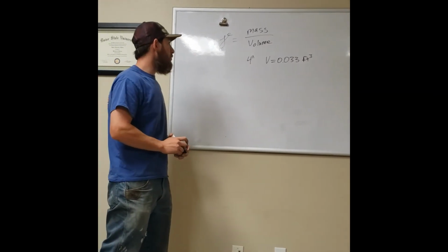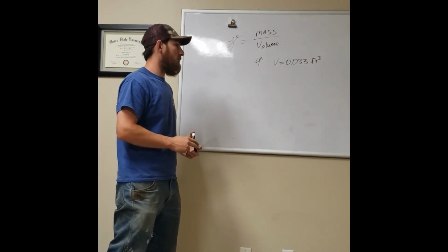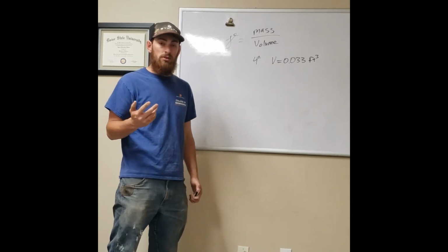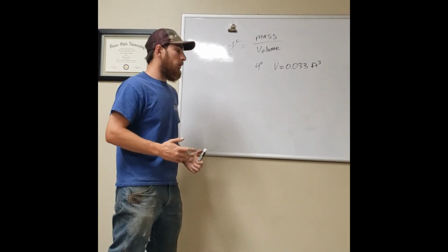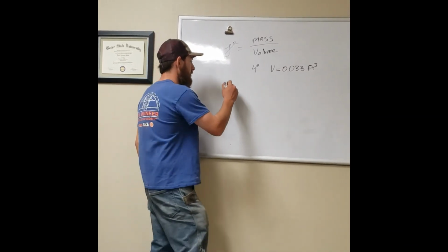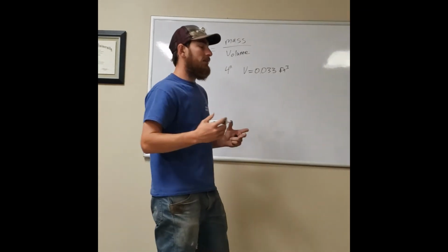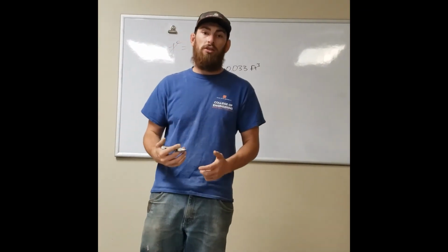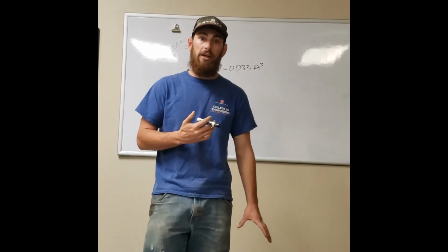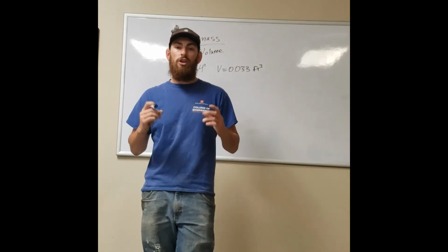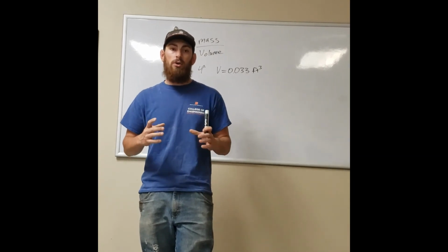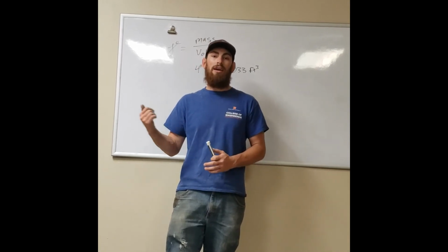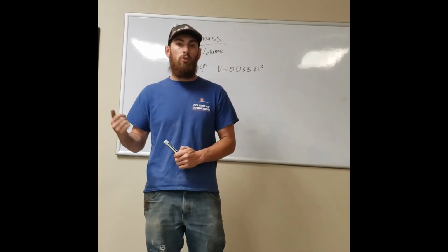What we will be doing is I'm going to follow one of the ASTM standards. The way that the Proctor works is we're trying to find an optimal moisture content. The optimal moisture content is the amount of moisture in the soil or in the aggregate base to where there's enough water in there to allow sliding of all your soil particles without bringing down your unit weight.